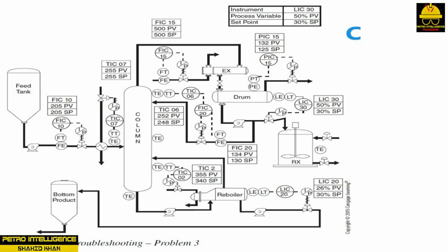In picture C, a full-scale process upset is occurring. The initial problem was the partial failure of the steam valve, TIC2. Look at the other process variables affected by the higher bottom temperature on the column. Problems in a distillation column typically include feed composition changes, puking, flooding, and equipment or instrumentation failure.